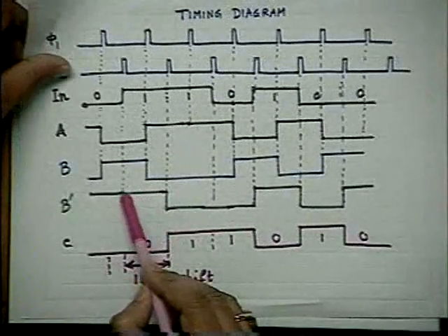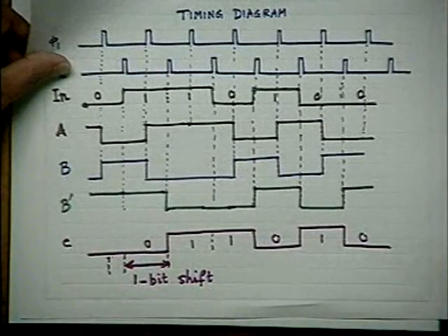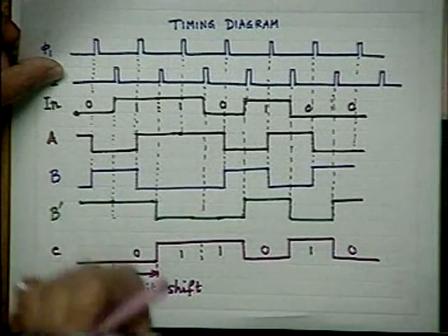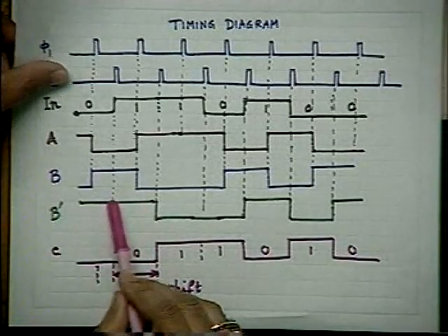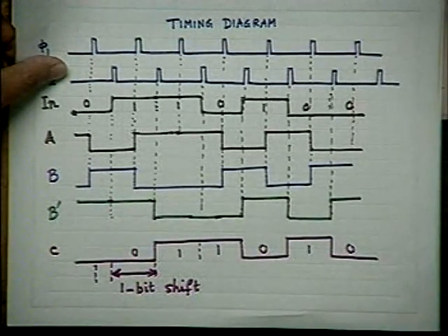So there will be a slight fall, not very slight, in fact around 1 volt fall. If it is a 5 volt thing, around 1 volt fall at this point, but not in many ways, only at those points where charge sharing is taking place. Please remember this, this has to be kept in mind.